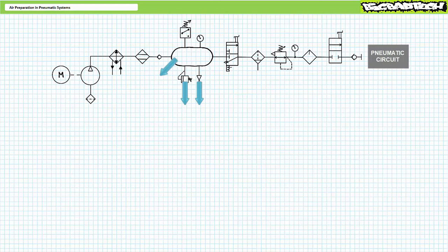Excess runtime per compressor might be caused by a leak in one or more of these components or a circuit. Opposite scenario. What happens if the pressure switch fails to open at the set value or is improperly wired to the motor control circuit such that it never turns the motor off? In this case, the compressor would keep running and running and running.